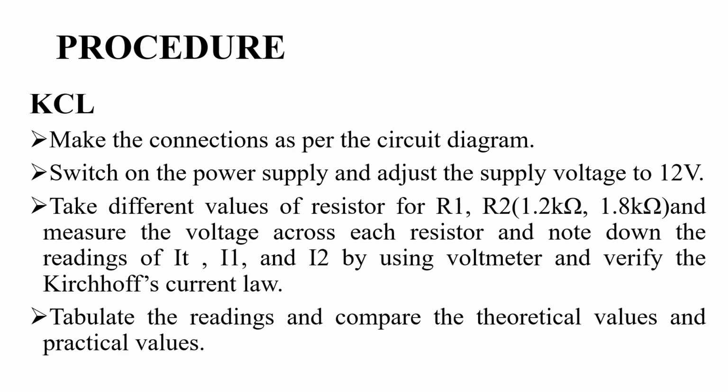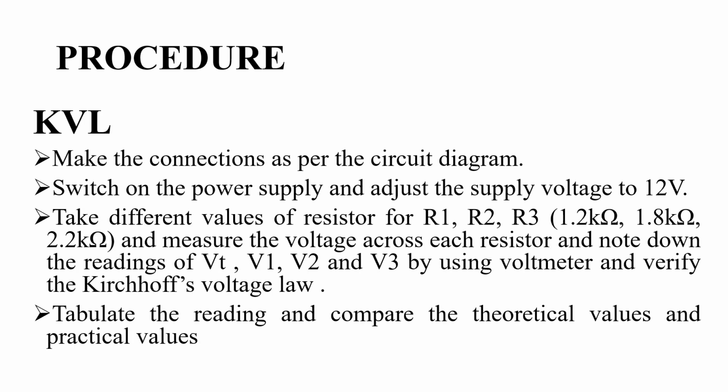If it is two resistors, take two different values of resistors. If it is three resistors, take three resistors of 1 kilo ohm, 1.8 kilo ohm and 2.2 kilo ohms, and measure the voltage across each resistor and note down the readings of V1, V2 and V3 by using a voltmeter and verify the Kirchhoff voltage law. Tabulate the readings and compare the theoretical values and practical values.